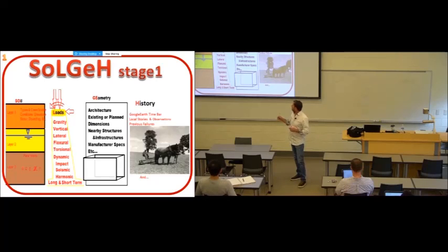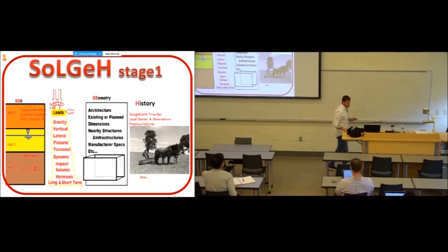And the geometry. Connect with the architect, get the geometry. What are we talking about? Sizes, dimensions, where are the columns? Are they close to each other, far from each other? And it's also related to the load. So they're all interrelated subjects, but you really need to collect all these before you start thinking about your problem.